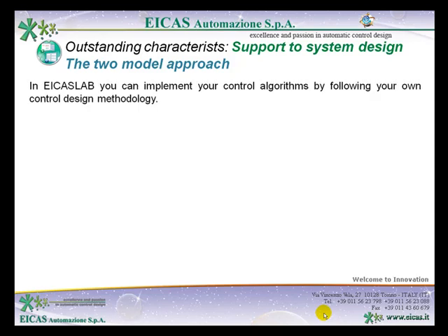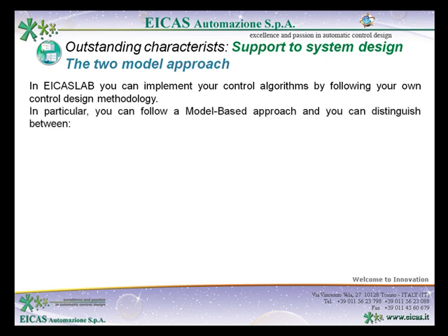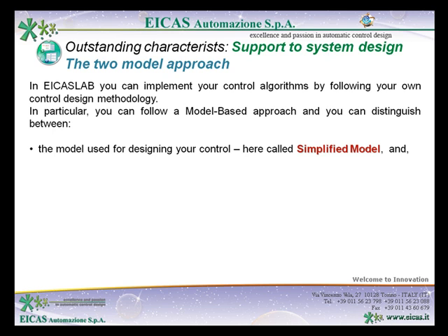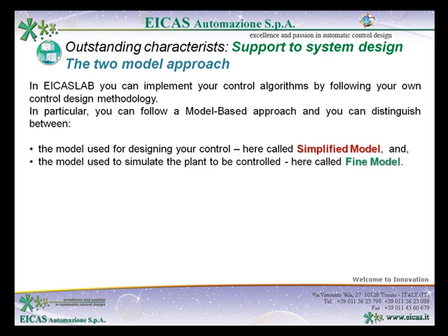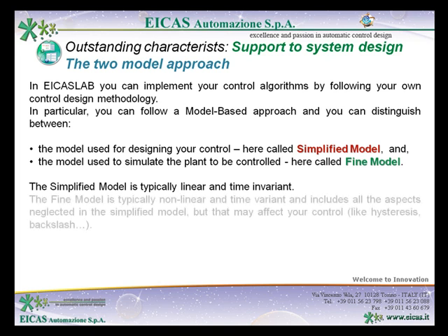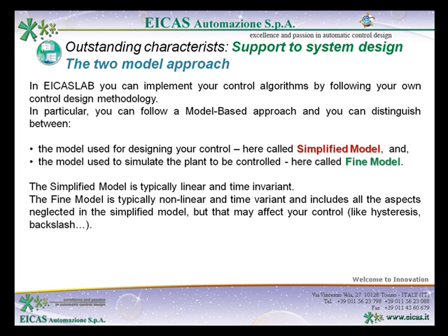In EICASLAB, you can implement your control algorithm by following your own control design methodology. In particular, you can follow a model-based approach, and you can distinguish between the model used for designing your control, here called a simplified model, and the model used to simulate the plant to be controlled, here called fine model. The simplified model is typically linear and time invariant, while the fine model is typically non-linear and time variant, and